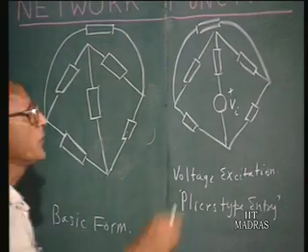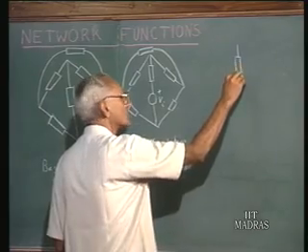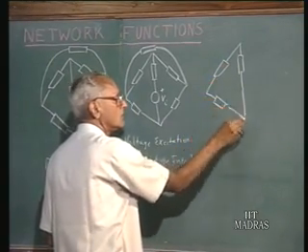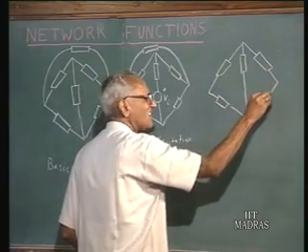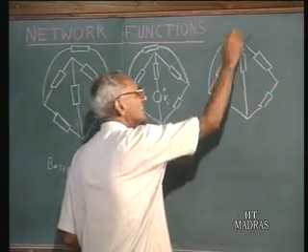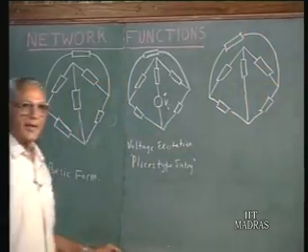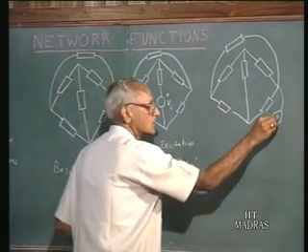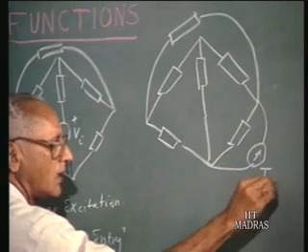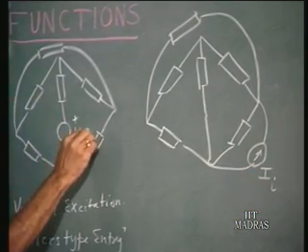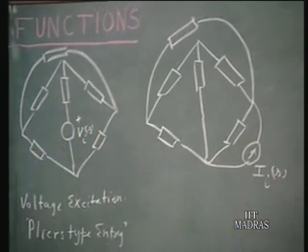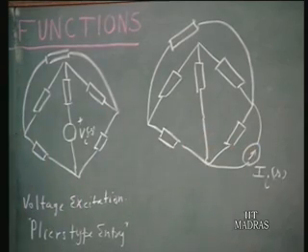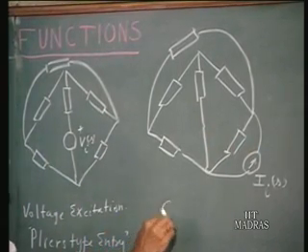On the other hand, if you want to introduce a current source, then the thing to do would be to introduce a current source in parallel with a particular element. Let us say this is the current source, Ii(s). So this is all we are talking in terms of Laplace transforms. So that when the current strength is made 0, that means this is open circuited, you get the original basic form of the network. So when you introduce a current excitation,